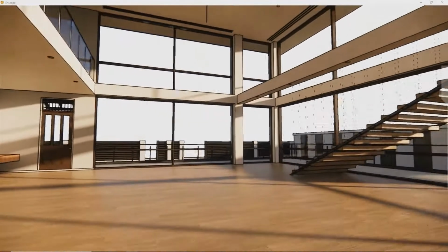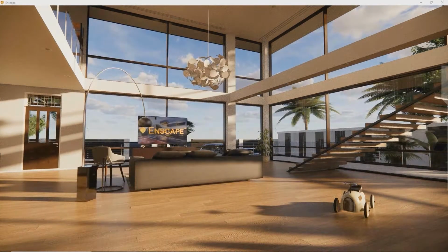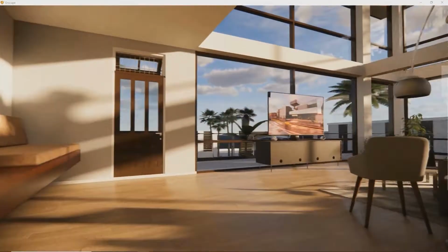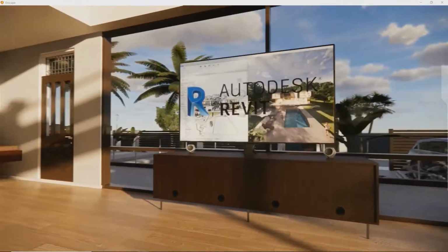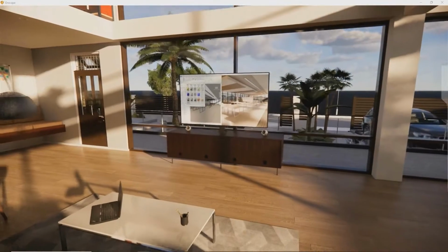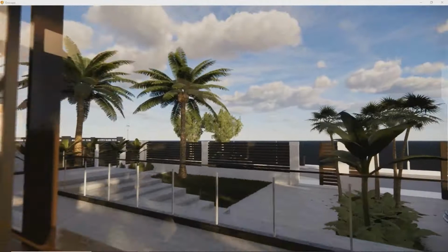With the materials set, we can use the families in Revit or the assets in Enscape's asset library to build out our final scenes. New in 2.9 is the ability to create custom assets and the introduction of video textures. We can apply video files as textures to represent any screen or to create special effects like fire in a fireplace.